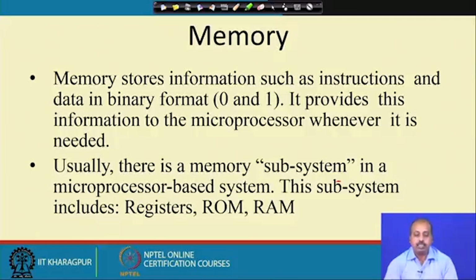In this type of memory organization, we have the same memory containing both program and data, so you cannot distinguish between them. Say I have a program that sorts 10 numbers, loaded from memory location 1000 onwards, and the data set of 10 numbers is stored from location 1500 onwards. Now, if by mistake the processor is told that the program is actually from 1500, where I have stored the numbers to be sorted, it will try to interpret that data as instructions and execute it, whatever be its meaning. That is garbage, but the processor has no other option. It will do it that way only.